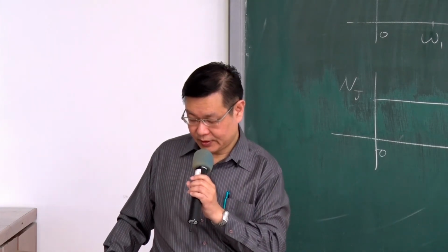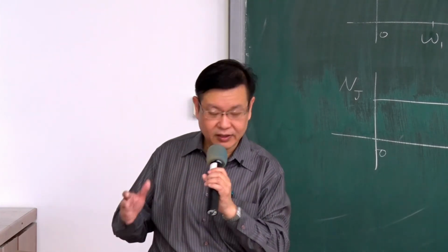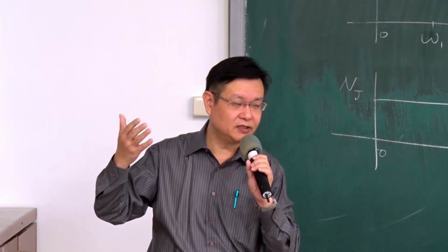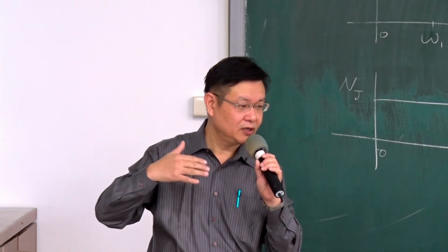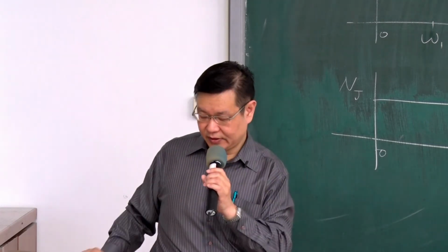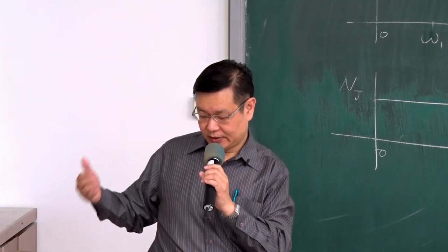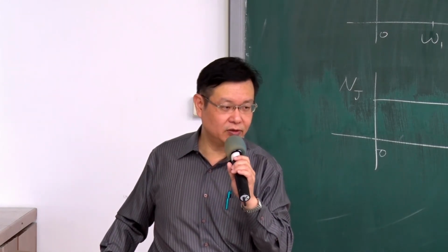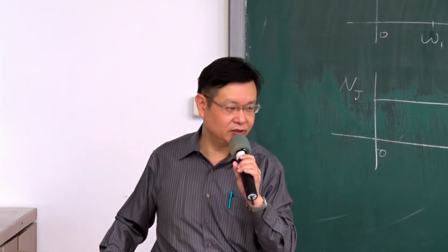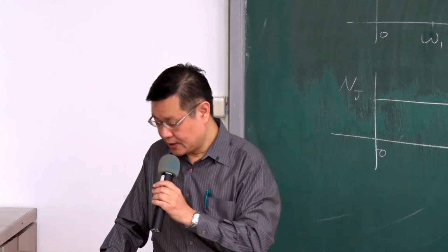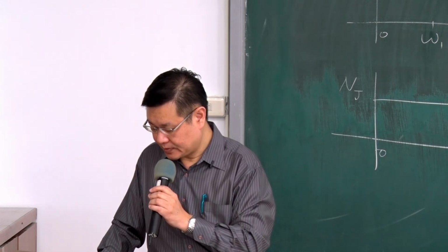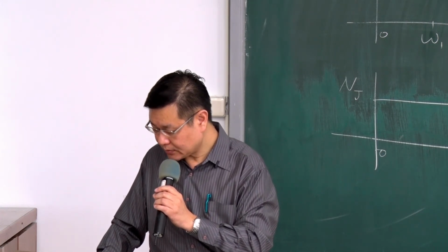So that's why we usually design our resistance in a range between tens of ohms up to tens of kilo ohms. It's very rare to design the resistance beyond hundreds of kilo ohms or even mega ohms. It's very rare. Okay, so this noise equivalent power.